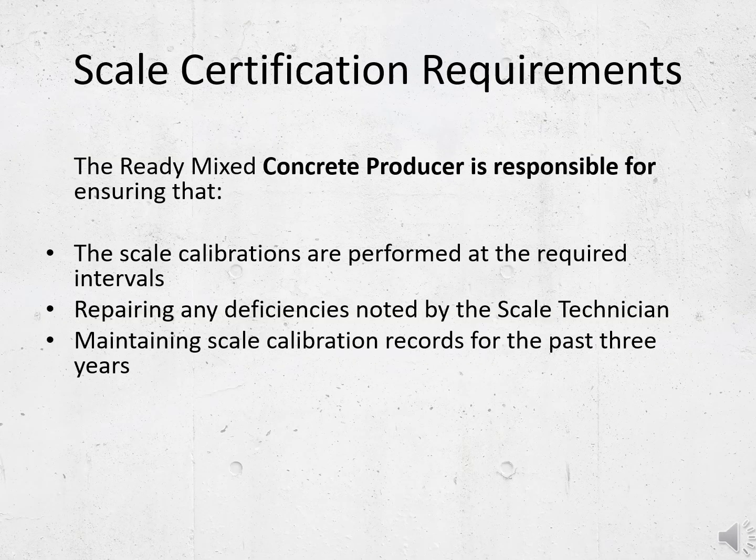Ask to see the scale calibration records for the past 3 years. Ask for service records for any repair work done in accordance with the deficiencies cited by the technician. Remember that any plant certification audit deficiencies cited by the inspecting auditor must be remedied within 4 weeks of inspection, unless otherwise agreed to by ARMCA and the inspecting auditor.